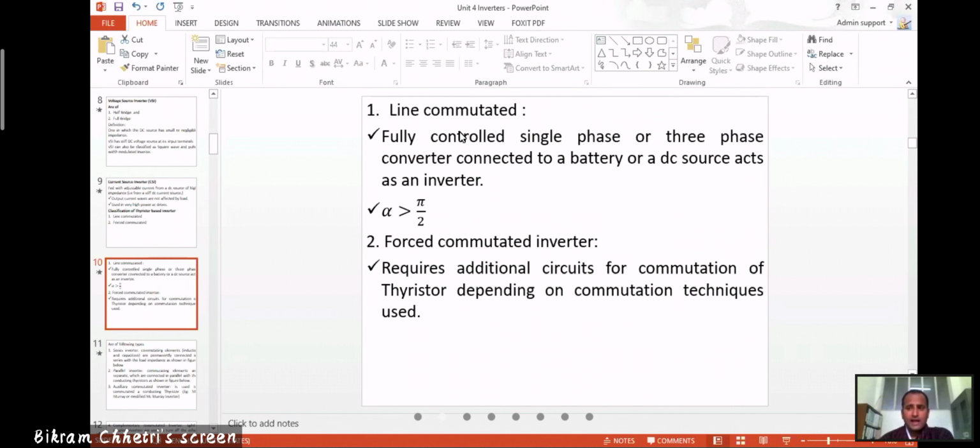But if we try to use a transformer to control the output voltage, the transformer will be affected if there are changes in the frequency. If the frequency is increasing, if we are talking about more than 50 hertz, then this transformer may not work properly. Maybe the transformer is designed for the supply frequency. So if we are talking about a frequency higher than 50 hertz, then this controlling mechanism may not be feasible, and you need to look at something with an internal control.